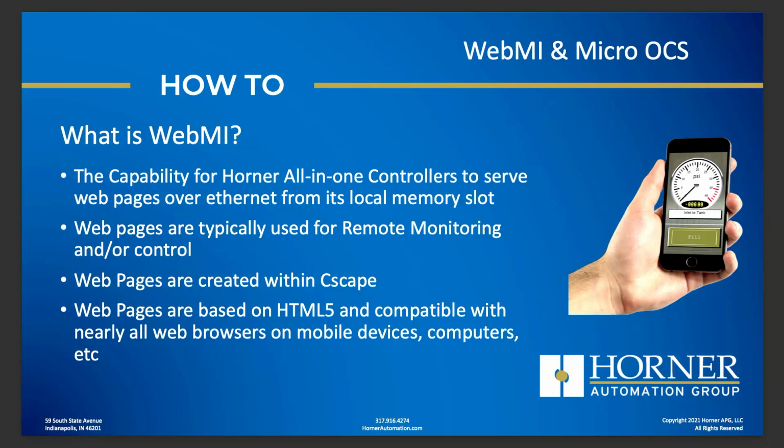All the objects that are available for you to put on an OCS screen are available for you to put on a web page. Now, the web pages that are created in Cscape are based on HTML5, and they're compatible with nearly all web browsers that are available on mobile devices, computers, etc. So regardless of what type of device you have, if it's a relatively modern browser that supports HTML5 based web pages, it's going to be compatible with WebMI.